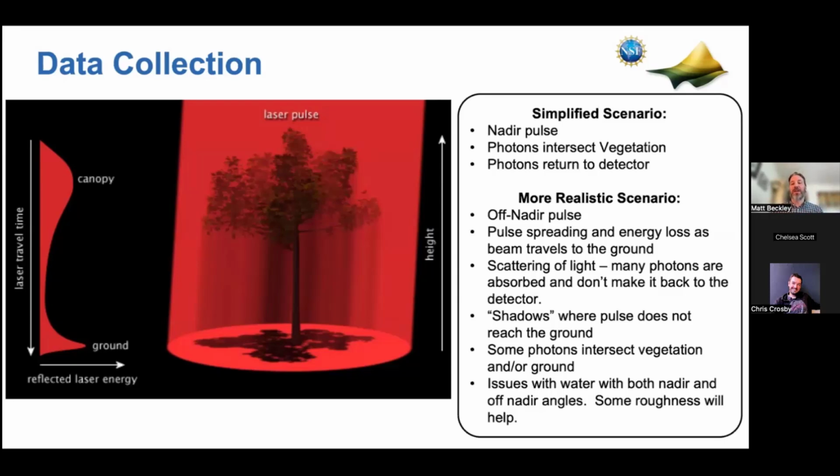One rule of thumb that I always tell people is that if you're on the forest floor and you look up and you can see bits of sky, any kind of light, you can get a LiDAR return on the ground from that. It is pretty amazing what LiDAR can do and where you can get a ground return from. There are obviously scenarios where you couldn't, like very dense tropical vegetation. If you can't see the sky from the ground, then you'd never be able to get a LiDAR return from that.